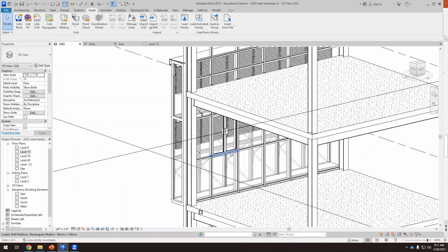We have this for natural ventilation. So when the temperature outdoors is good enough, not today, we open that window and we don't need to use the air handling unit. Okay, so in this kind of advanced double skin facade, human beings do not make these kinds of decisions. It's kind of scary, but different sensors make those decisions.